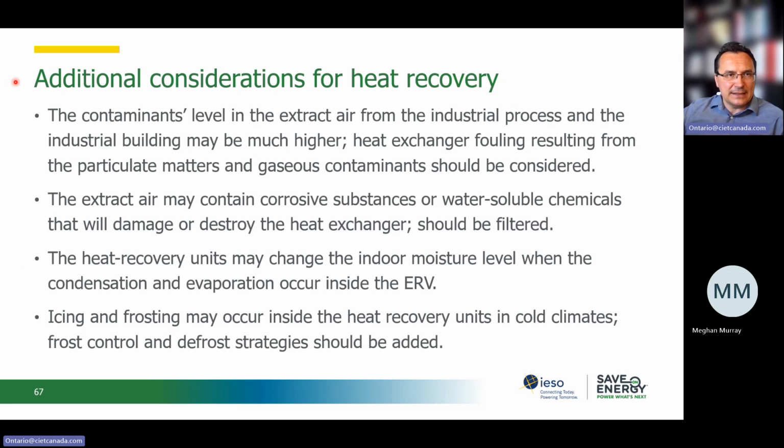So if we look at additional considerations for heat recovery, yes, heat recovery is an important element that we focus on, but we have to be aware that the extract air, the exhaust air that carries the heat, may also contain a higher level of contaminants.